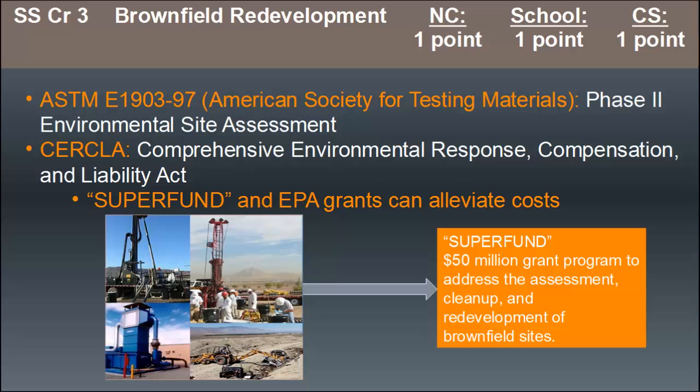In situ, it's better on site if it's done wisely. So treatment on site could include injection wells and reactive trenches. Could use natural hydraulic gradient groundwater, which only requires minimal disturbance of the site. Bioremediation is the best, utilizes microorganisms and vegetation to remove contaminants from water and soils. It's an alternative to landfilling and incineration.